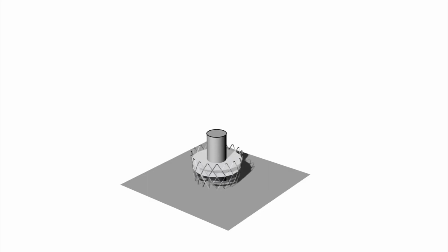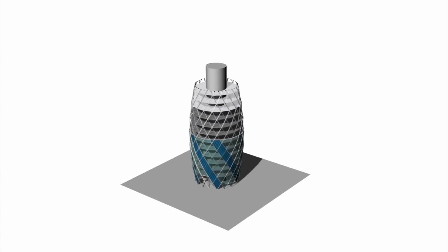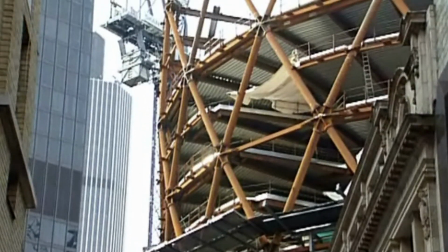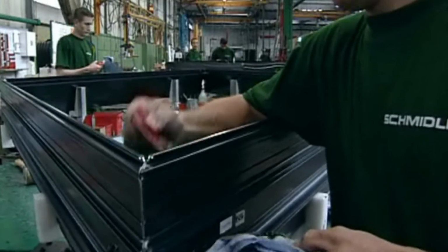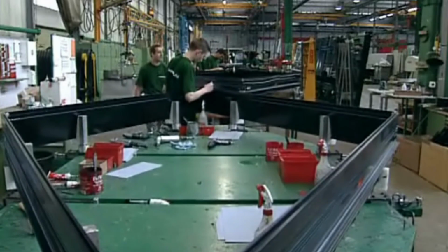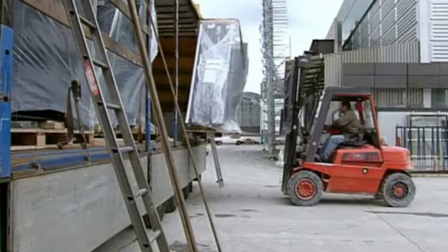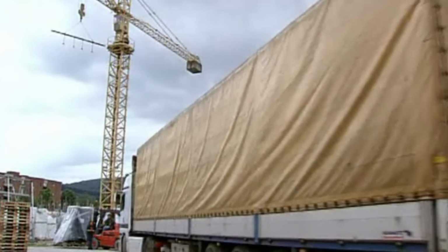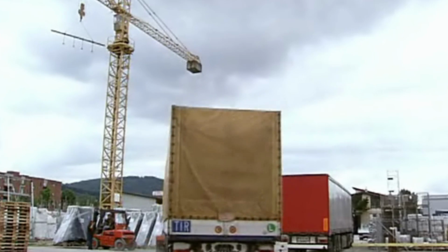These three construction processes occurred continuously and simultaneously. The diagrid structure of the Saint Mary's building was very important in the manufacturing and construction quality of precise steel members. Diagonal members and nodes were pre-made in the factory and transported to the site. Due to the small site, it was not possible to load all steel in advance, so they chose to continuously supply factory-made members to the site.